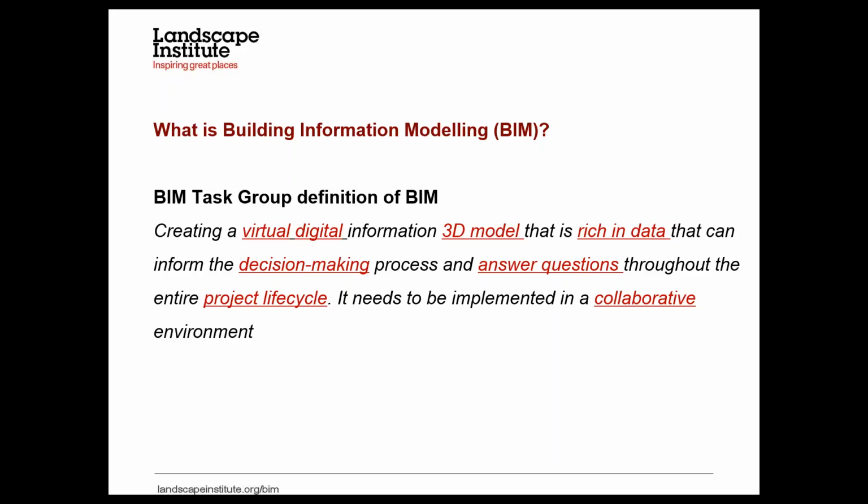It talks about a 3D model. Some of the projects you're going to be involved with won't need 3D. Where it is essential to make proper design decisions, then 3D is relevant. But there's no point in saying that BIM is 3D if you don't need 3D. If it's not answering the question, what is the purpose of the 3D? That's what BIM is all about, asking the right questions to know what you've got to deliver. So don't think that just by delivering a 3D model you've cracked BIM, because in most cases it might be other information rather than the 3D that's critical to answer the questions.